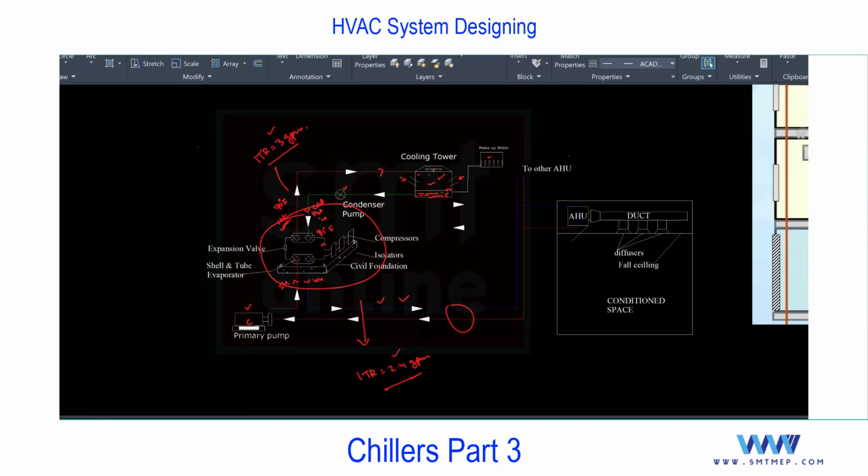We're using brine solution, water mixed with the glycol or propylene. We have different chemicals, and that solution we used to call as a brine solution, and with that we can reduce the freezing temperature of water to -4 or less than that. Okay, means still in ice manufacturing they are using the brine solution. Yes. Even in this cycle also we are using this for n number of reasons. We are not using the normal water. We are using water with the glycol or propylene that we used to call a brine.